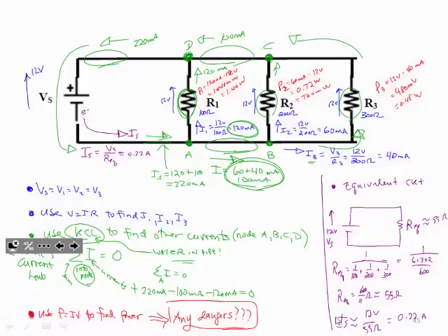And I just inserted my ammeter, right, coming right through here. And what am I getting? I'm supposed to get 120 milliamps. Am I? Yeah, it's 0.12. Now, this is actually within my range, so I can switch to the lower scale. So I'll do that. I'm going to pull this out. I'll bring this down to 200 milliamp range. And so there you see, I'm at 123 milliamps.